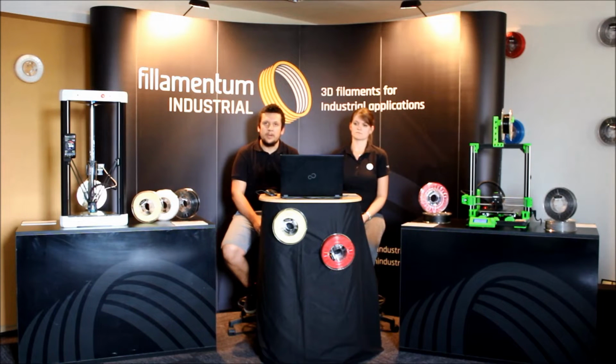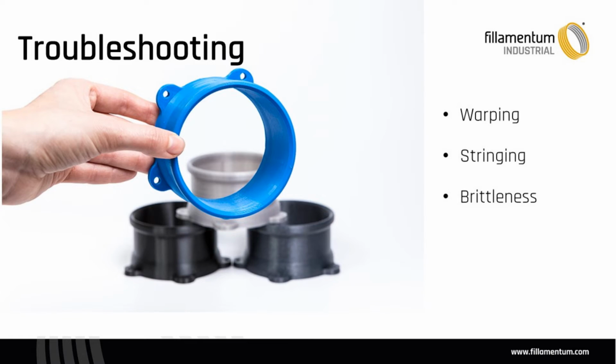As we mentioned before, keeping the filament in airtight bags with desiccants is really important. Also, in fewer cases, the stringing could be caused by too high a temperature of the nozzle, because you melt too much and the filament is leaking too much.